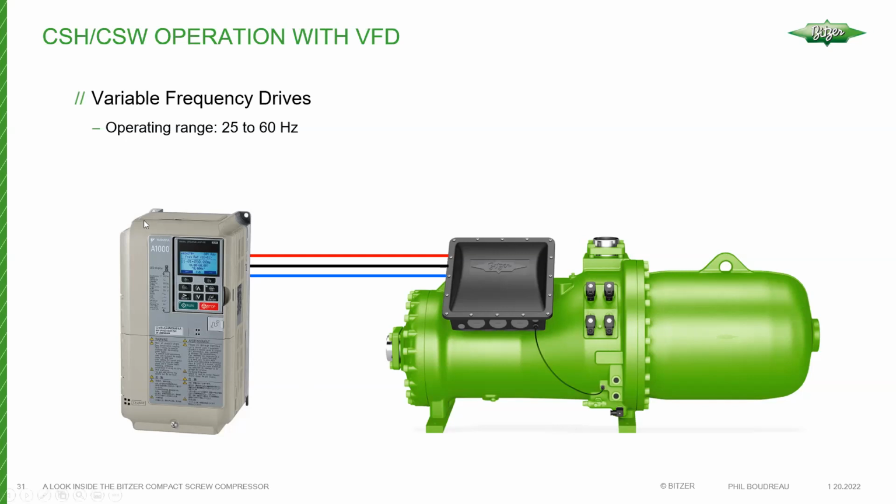It would require basically a VFD, which takes your 3 sine waves that come into the VFD, and they're actually converted basically through rectifiers to a DC voltage, and then it goes through a transition circuit, where the voltage is stored in capacitors as a DC voltage, and then the output circuit is basically just taking that DC voltage and pulsing it to produce basically a quasi kind of sine wave to run the compressor.